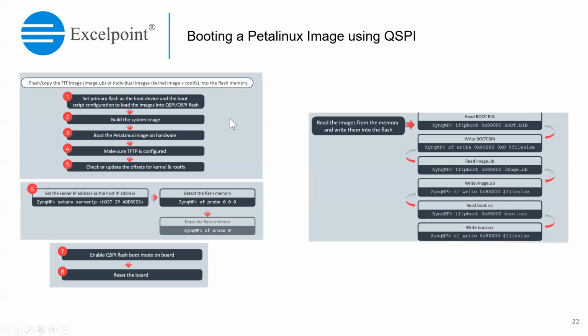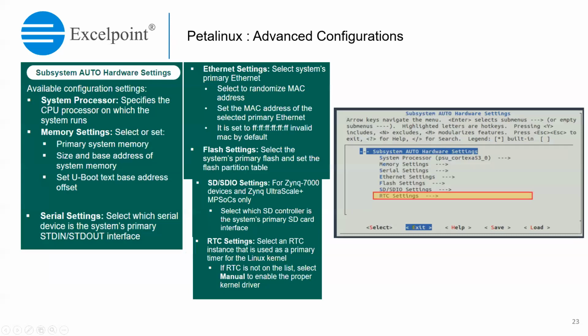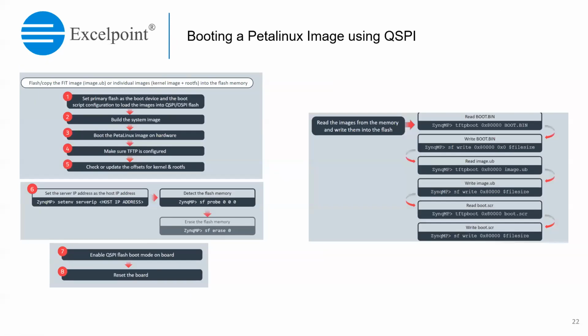So, Christoph, just very quickly, whilst you're still on that slide, there has been a question asking about boot arguments. What are the boot arguments which should be updated in the system-conf.dtsi to then boot from the SD card or USB? Is that something that you could maybe touch on at the end? Or we'll go through building, and then maybe when we go through the build and actually do some configurations in the Petalinux tools, it might become clear. Thanks. So yeah, we can come back to that later.